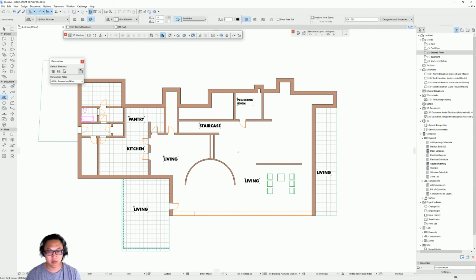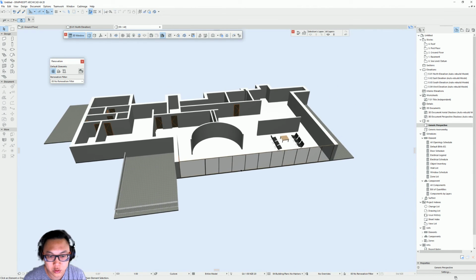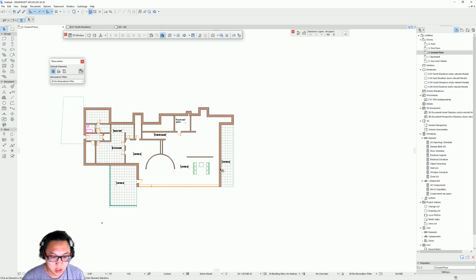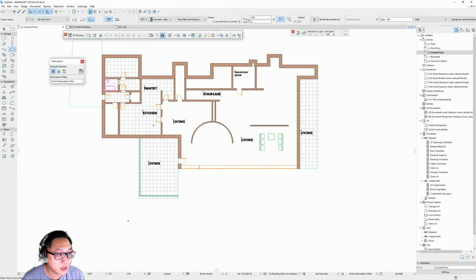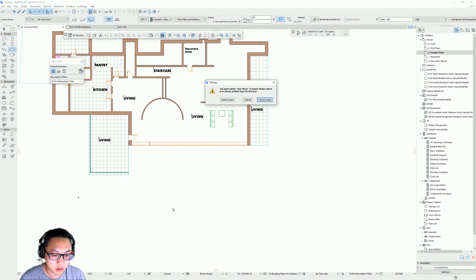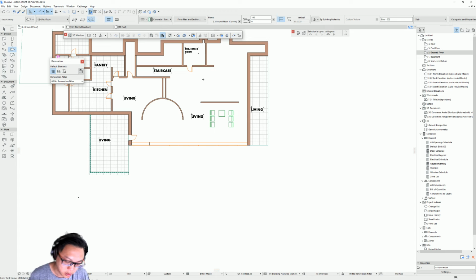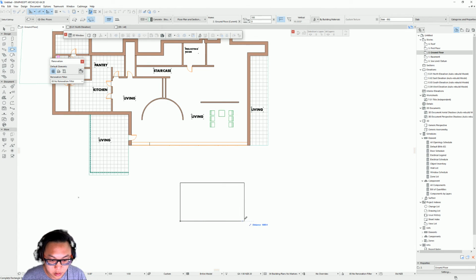Okay, I think I'll just stop here for the tutorial. Maybe let's have a quick recap. So if you want to make a slab, just click on the slab tool. Different methods, either you can use the rotating rectangle. Usually, if you want to make square or rectangle shapes, it's faster. Oops, the floor is locked, so I have to go back to control layers, unlock this, press OK. So you can have your slab,